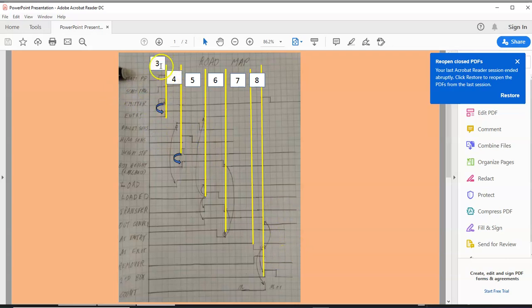For instance, if we're in this step 5, for our outputs, we have the entry conveyor on, we have the load conveyor on, and during step 5, those outputs stay in that frame until we get that transfer trigger, is what we call it, and then we just jump to a different set of circumstances.